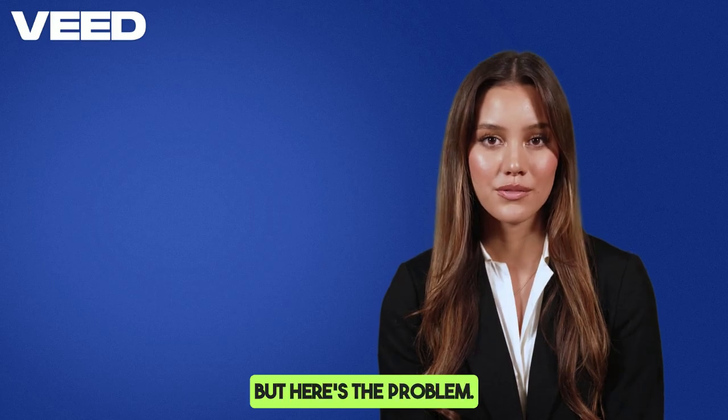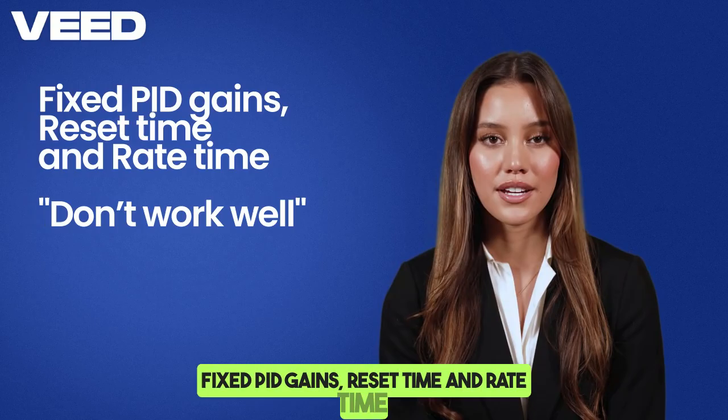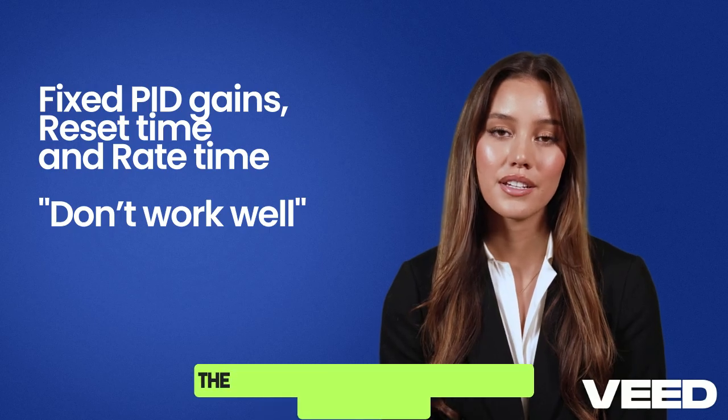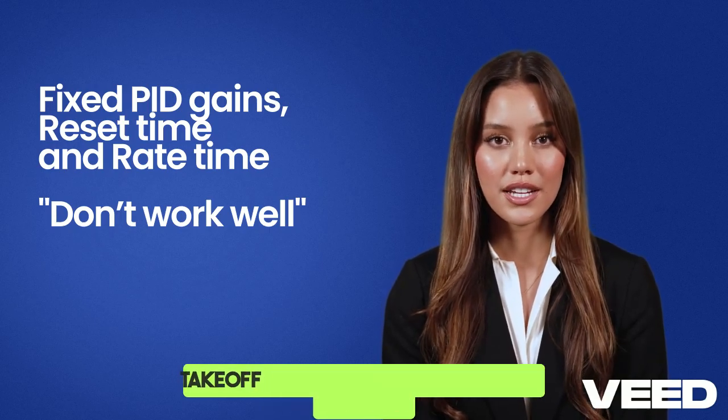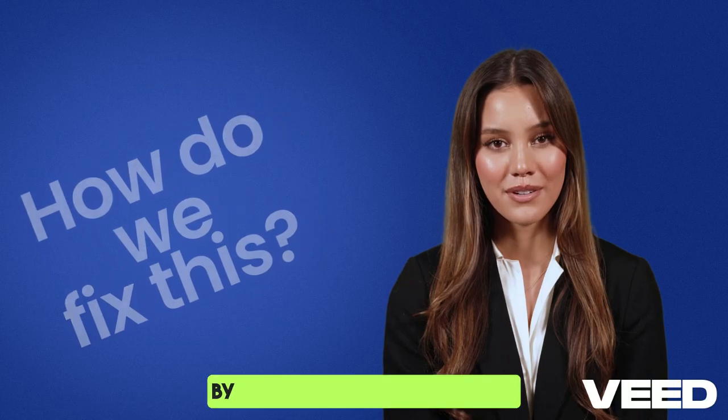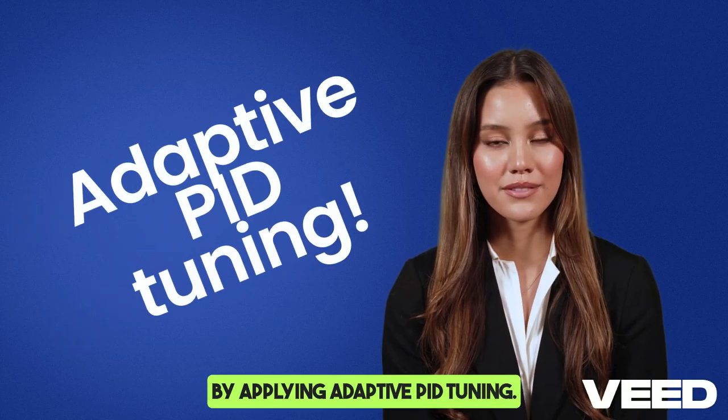But here's the problem. Fixed PID gains, reset time, and rate time don't work well across different speeds and altitudes. The same controller settings that work during takeoff may cause instability at high altitudes. So, how do we fix this? By applying adaptive PID tuning.